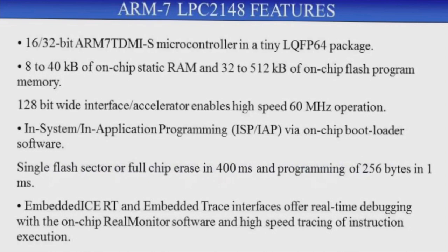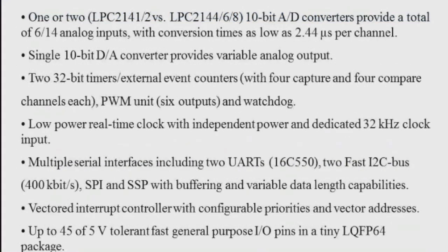It also has a single flash sector or full chip erase in 400 milliseconds and programming of 256 bytes in 1 millisecond. The interfaces offer real-time debugging with on-chip RealMonitor software and high-speed tracing of instruction execution. It has one or two 10-bit analog to digital converters and provides a total of 6 or 14 analog inputs, with conversion times as low as 2.44 microseconds per channel.